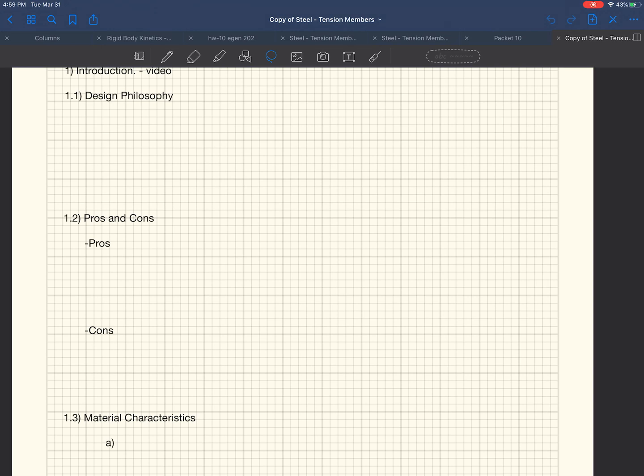And so the steel fabricator will get these raw sections from the steel mill, and then they do the fabricating. What I mean by fabricating is they cut them to length and put the holes in them. If they're going to have bolted connections, they drill the holes and everything, and they get it all prepped for shipping and ready for construction, right? I think the word that is used, and I don't like to use it, is erection. They prep it for erection, okay? That's the technical term that gets used in steel design.